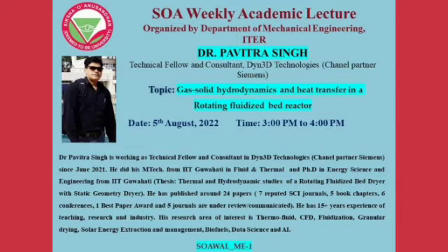And this is the detail about the gas and solid phase. So the density of gas is 1.225 kg per meter cube, and for the solid it is 800, and the thermal conductivity is 0.0242 for the gas phase, and for solid it is 0.045, and the specific heat capacity is 994 for the gas phase, and 800 joule per kg Kelvin for the solid phase. So these are the boundary condition parameters used in the simulation and the gas and solid phase details.